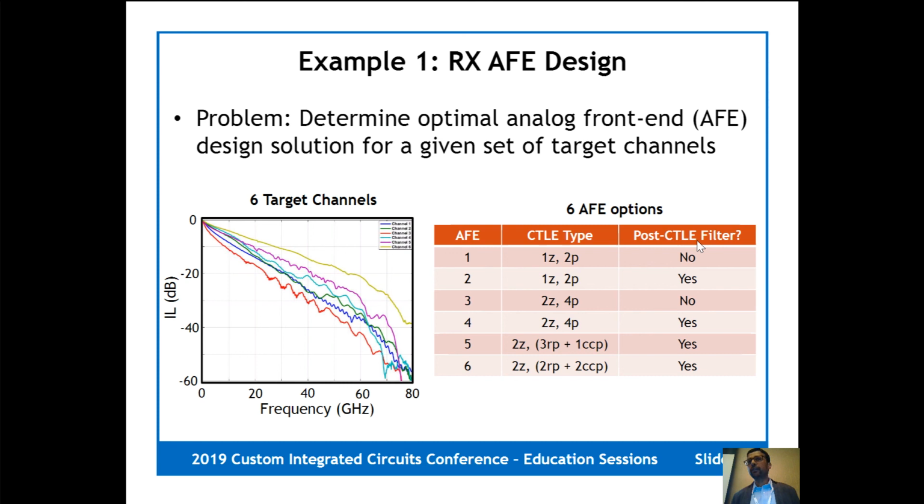Like people are looking at PAM4, which is not sufficient to give us the 2x, but it gets us partway there, and then an increase in baud rate. People are also looking at QAM-32 type higher order constellations in order to limit the baud rate. So I'd say that's still open.